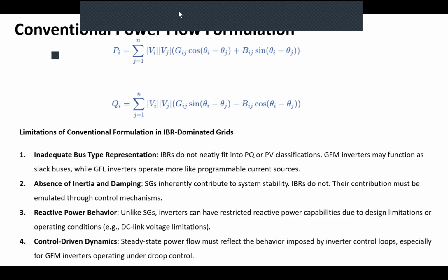So now, what does that mean? What are the known variables on that parameter, on that control system? Active and reactive power. So now you have a slack bus that relies on PQ. Now, how does the inverter control understand PQ? They have to measure the voltage and current, or the frequency and voltage at the terminal, to calculate what the reference P and Q is, so they could set their own V and Q.